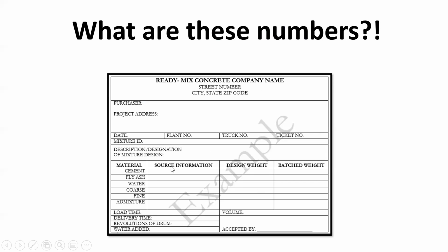And you may even have a description if they need a description down there. It's pretty common. They may just have the description in the ID. So instead of saying this is mix 1, they may have the description in that. Like I kind of said, 3000 PSI, no air entrained, residential floor slab. You may also see the material information, mix design information, and that's kind of what we're going to focus on, is how all that actually gets communicated.